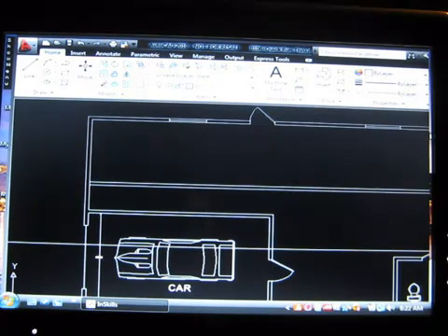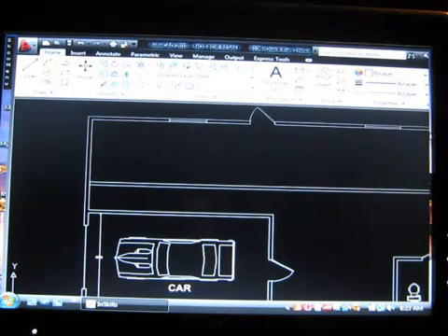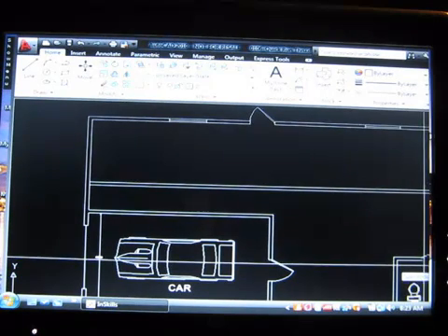Now, once we come in the building through the top door, we can't get to these other rooms. Let's add a door. We will copy the door that's already in our file. CP for copy, press enter. Now select the door. You can select this door, you can select that door, it doesn't matter. You can even select this door, it's fine. Pick it, press enter. Now we need a base point.